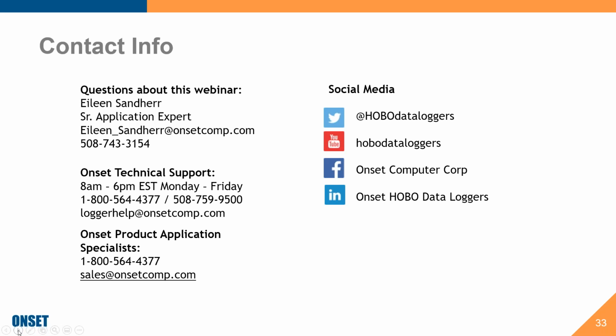And if you're using a nearby weather station, for example, as soon as you save that data file, and let's say you save it to your desktop and you use that as your default, the HOBOware Pro software will remember that, and it will access that and say, is this what you want to use? And it's going to give you a few click-throughs of, yes, I'm in freshwater or I'm in saltwater. I'm using this for barometric pressure. Another click, it will plot your data and do that barometric compensation assistant for you.